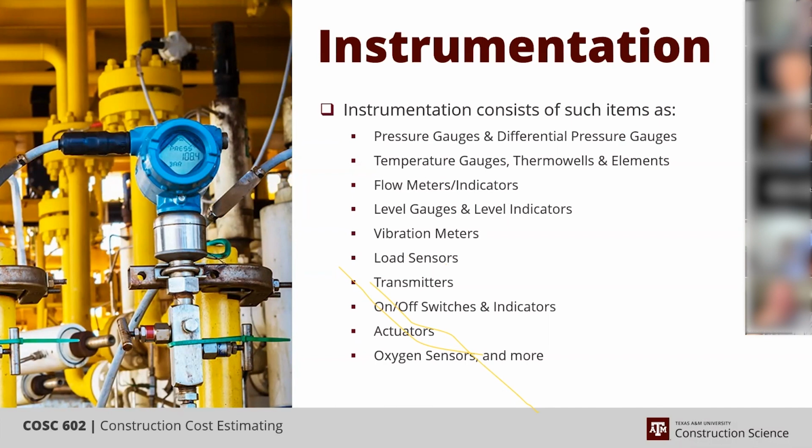Yeah, very good point. Very good point, Stephen. And I use the example of screwing in that temperature gauge directly into the pipe of the tank, and it tells you what the temperature is, versus the thermal well. And like Stephen's saying, that thermal well, it's threaded in and sealed with the shell of whatever it's in, and the element can go in and out without opening that.